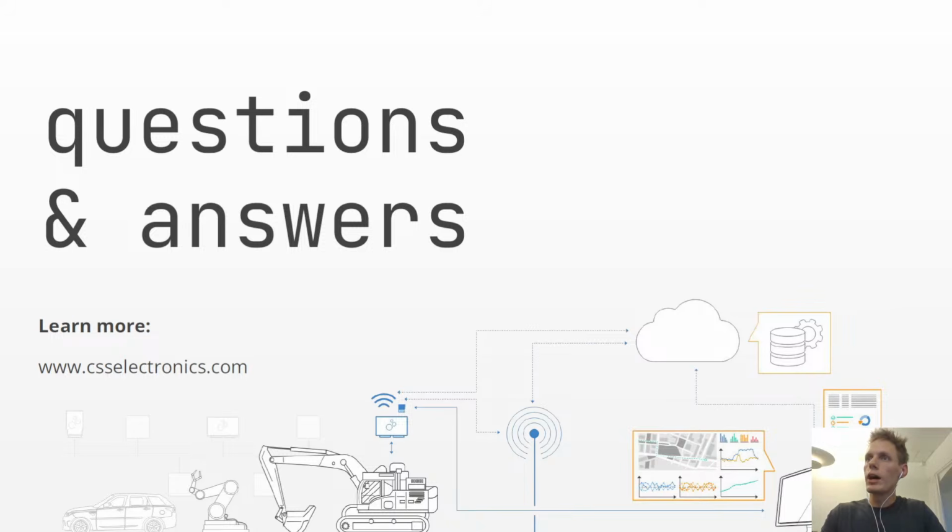There is a question on whether you can get the data directly without a software or server. And I think we covered perhaps that on the server side and on the software side. So there are many different ways you can extract the data. At the end of the day, for all of the devices, you don't have to use a server. They can work offline, whether it is the CANedge 1, 2, or 3. So if you don't provide a server, it will just accumulate the data on the SD card, and you can always take it out.